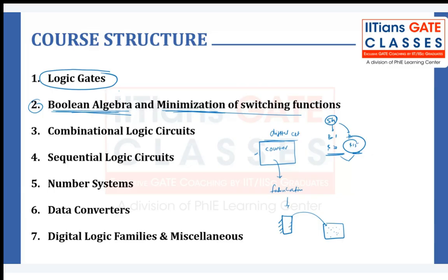That is one of the premium and important points that we have to learn whenever we are going for Boolean minimization and switching functions, right? You might have heard one term, redundant logic. Number of components reduces, switching time is also reducing, correct? Switching time will reduce, noise will reduce, power will reduce. If you can implement the same logic with fewer gates, then it will consume less power, less heating, less drain on the battery, capacitor discharges, many things are there.